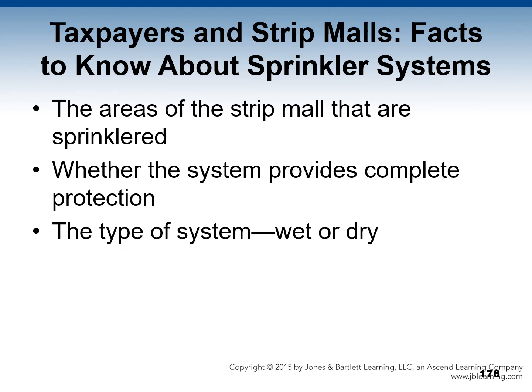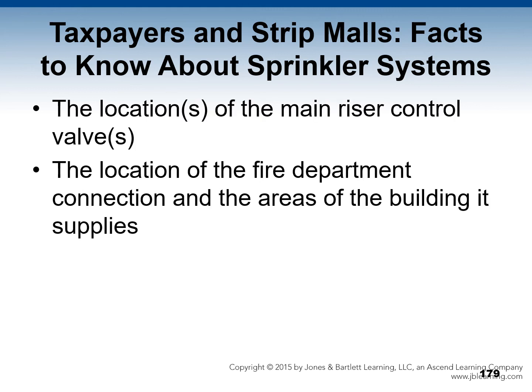Note that many strip malls with unheated attics often leave unleased tenant spaces unheated, necessitating a dry system. The location or locations of the main riser control valve or valves is, of course, important to know, and be aware that these could be hidden in a closet of a tenant space.